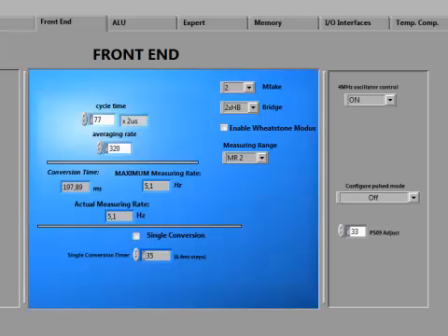The number of discharging cycles needed to make a complete ratio measurement depends on the setting of the number of bridges. Each half bridge contributes to 2 cycles of measurement. Thus, a full bridge needs 4 cycles and a quattro bridge needs 8. The number of times this complete measurement ratio has to be measured to calculate one measurement value is given by the setting of the averaging rate configured here. The conversion time and the maximum allowed measuring rate are updated here automatically.